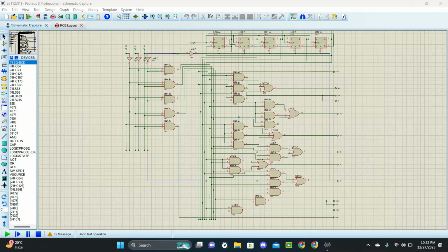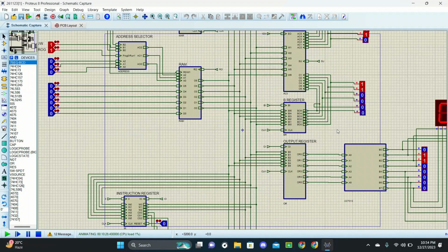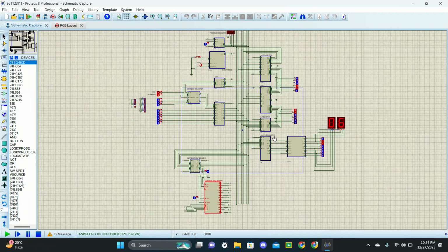As in our 6-bit SAP, each of the components is of 6 bits, where the first 3 bits are called the opcode, which defines the instructions the component has to do, which are loading the data, addition, subtraction, output, and halt. The next 3 bits pass the address field in the instruction, and control bits are unchanged in the T state. So let me introduce you to our next component, which I'm going to describe, the